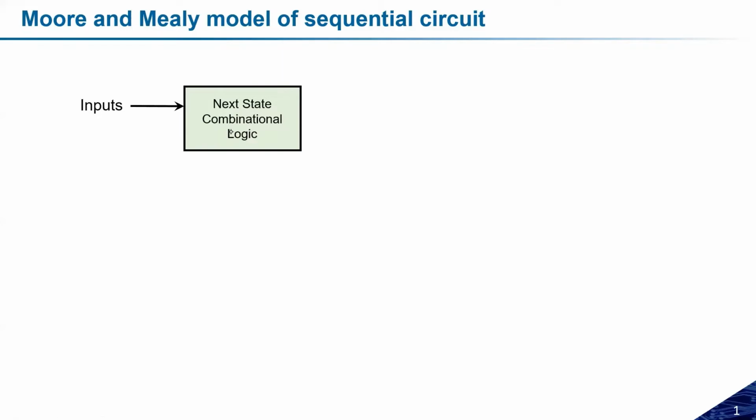The difference between sequential and combinational logic is that if there is some memory or storage element after the combinational logic circuit, then we can consider it a sequential one. Sequential means they have some storage capability, they can latch some data.